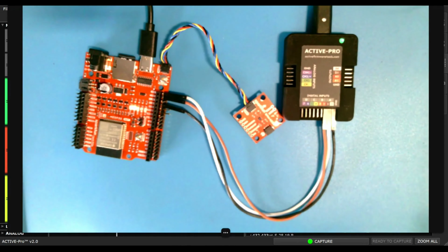Now let's switch over to the IDE for that processor, and let's start writing some code. I want to show you how to do that right now. So here's the IDE for the ESP32 firmware that we wrote. It's Arduino IDE. It includes the BMA400 accelerometer module as well as the BLE module. It's pretty simple. It shows the setup routine, which initializes the I2C, the BLE module, as well as the accelerometer. The loop is actually doing the work of this application.